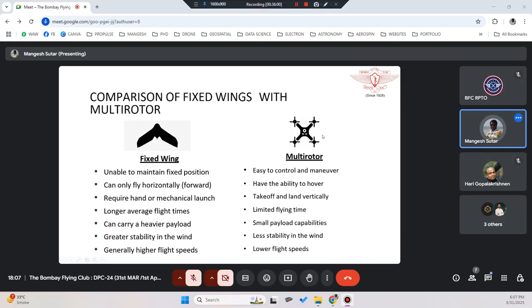Okay. Again, see, these multi-rotor drones that we flew are not aerodynamic, because they are not designed using aerodynamics. You can see the Phantom drone more or less is aerodynamically designed, but still it's not that aerodynamically suitable. It is made stable by using avionics. It's not stable because of the design. It's made stable because of its avionics. Okay, we'll see in future topics. So, small payload capacity. Multi-rotor normally carries maximum an RGB camera, thermal camera, or lidar, or maybe your spraying tank, seeding tank, or a payload of 2 kg, 5 kg, 10 kg max.